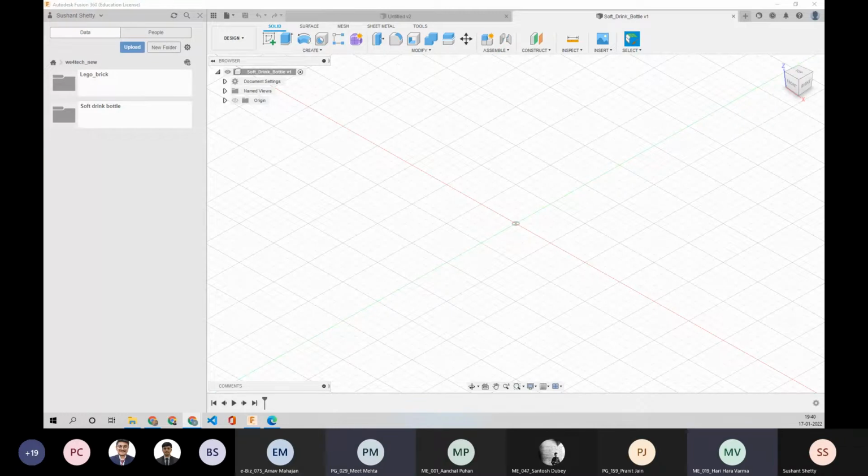Once the extrude is done, if I want to change anything, how do I edit it? Or how do I edit the sketch, if I want to change the dimension? Okay, at the bottom of the screen you see there are different options. My screen is still visible, right? In the bottom panel, you can see your sketches or the extrusion that you've done. If you go back, there you can change your dimensions. Was it helpful? Yeah, got it. Thank you.